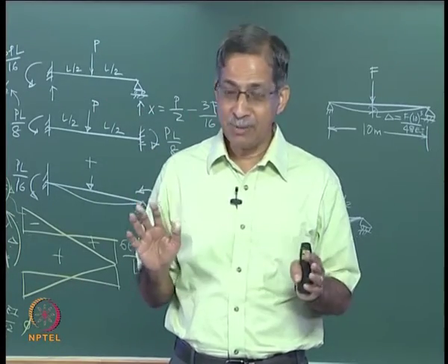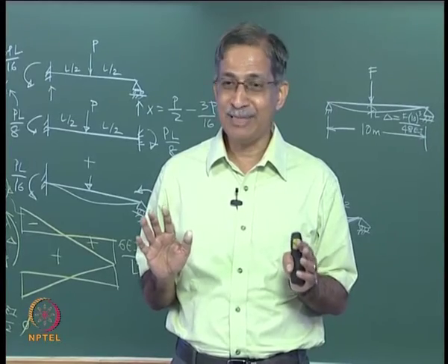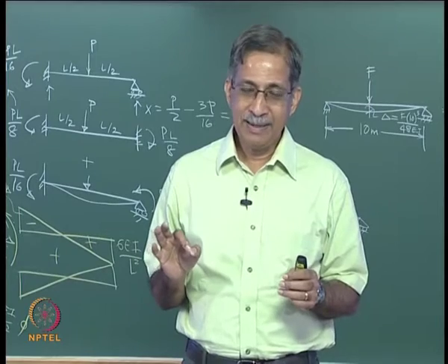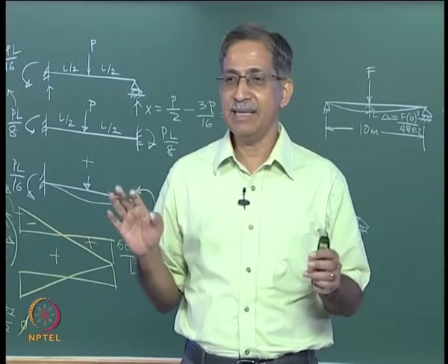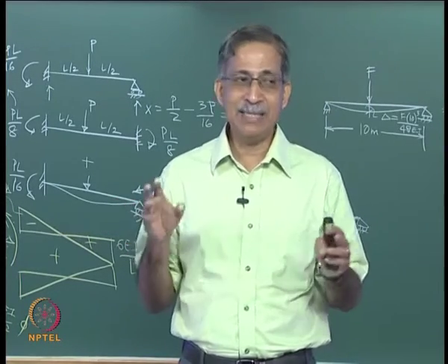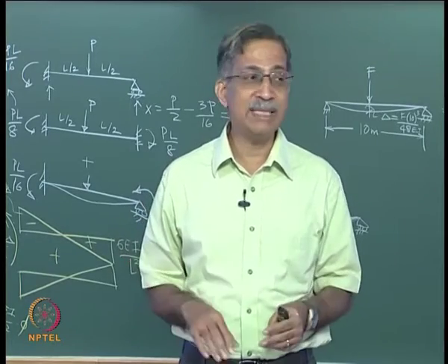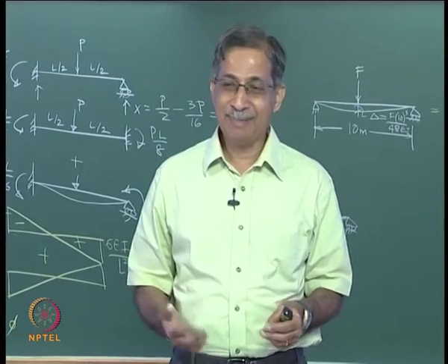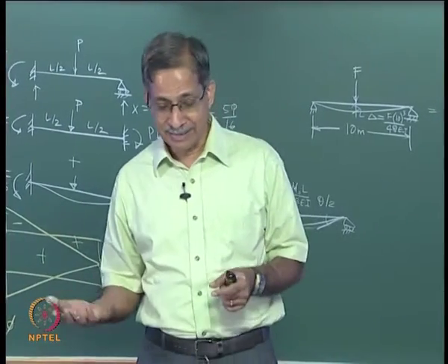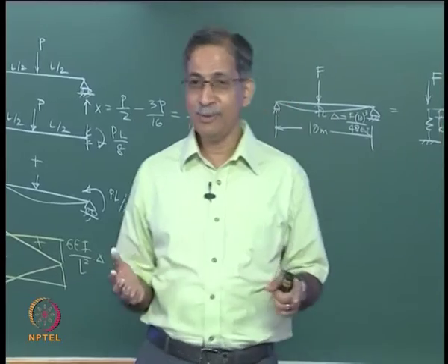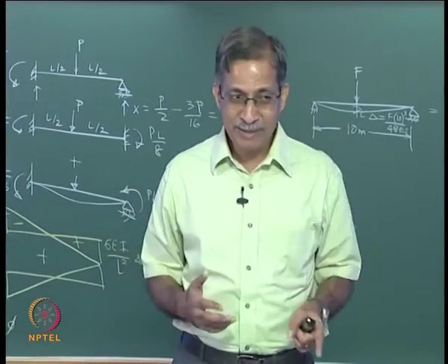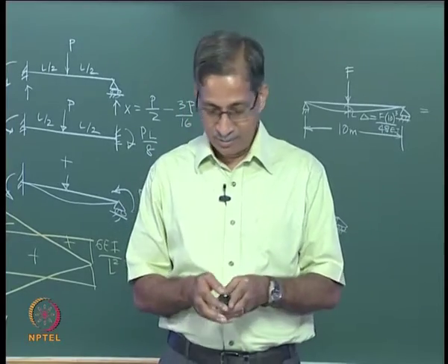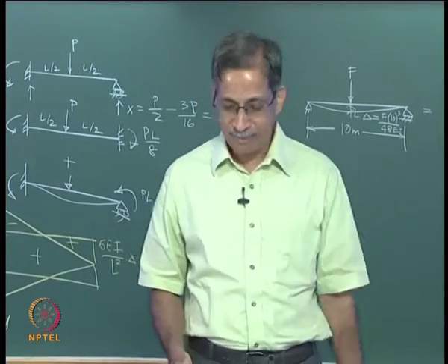When it came to lateral load, it took some time for them to work out a simple way of cracking the problem, and they came up with a brilliant idea. They said, let us make some assumptions and make that whole frame statically determinate. So some methods evolved over centuries and they are still popular today. How do you convert, and I want you to give me the ideas, how do you convert an indeterminate frame to a statically determinate one for the sake of approximate analysis.